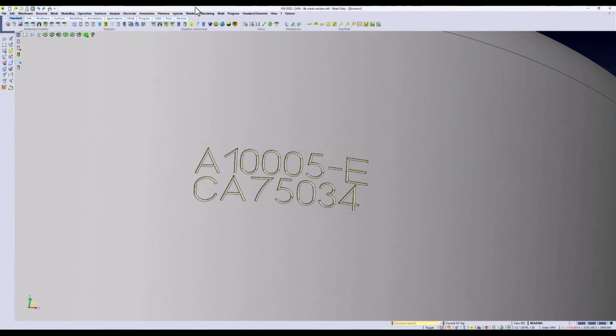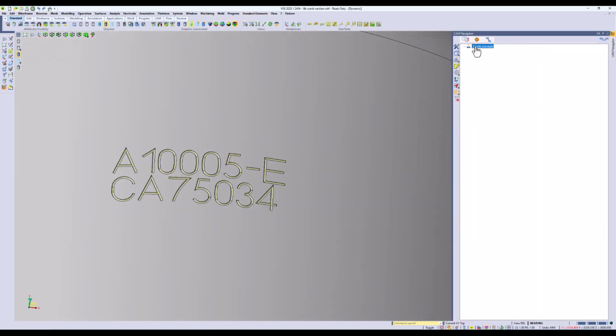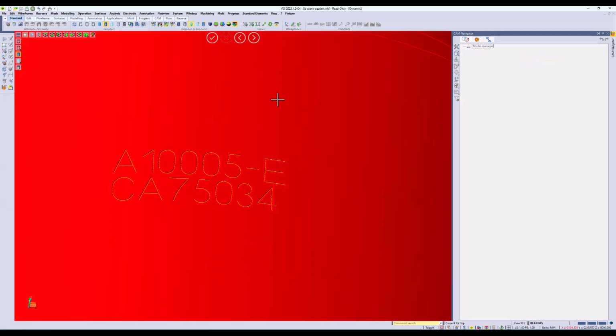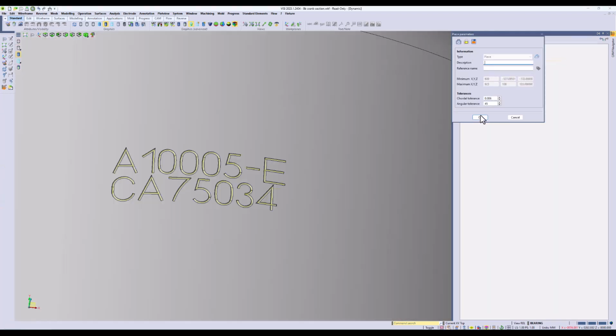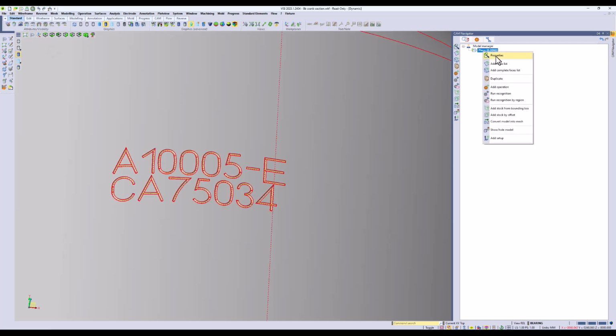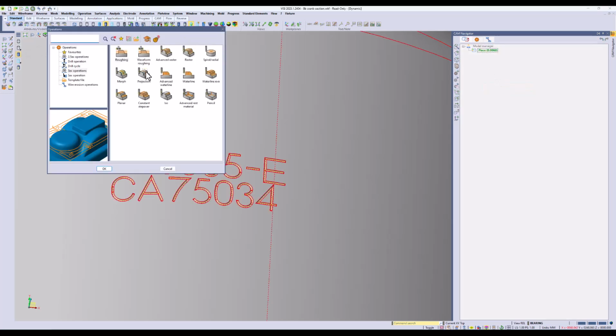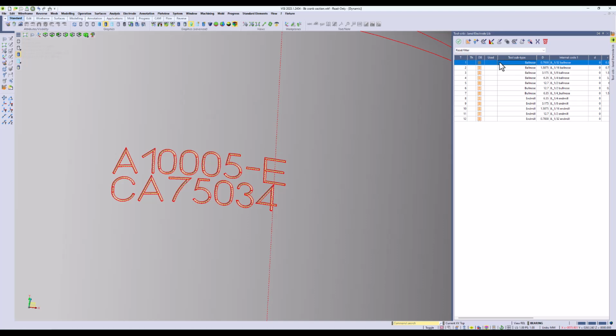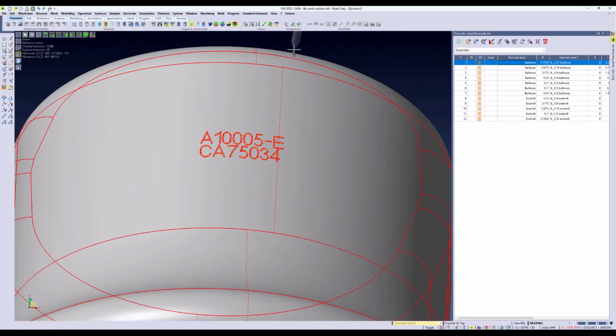So now let's do some machining off of this. I'm going to go into Cam Navigator. I'll add a model into this area. That model is going to be used for 3-axis work. And inside of this piece management, I can look up my 3-axis machining. From here, I will select the projection command. Projection is used specifically to cut a profile or cut right on a line to be able to create the engraving text. I'll select my tool for engraving.